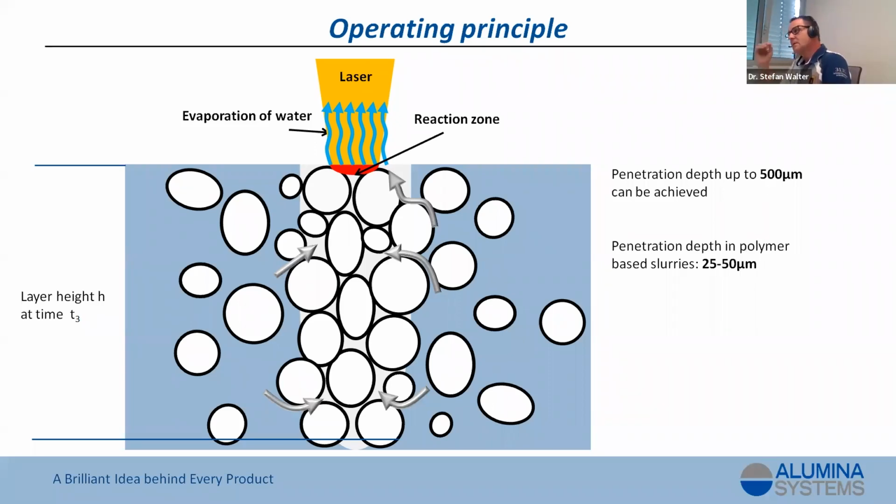Yes, it could. Usually after you have printed these parts, you have to dry them in a furnace, at 40 degrees, something like that, quite slowly. After that, you can store them for weeks or at least a month or two. You should take care that the part does not soak water into the body again. It should be dried and stored. That would make sense.